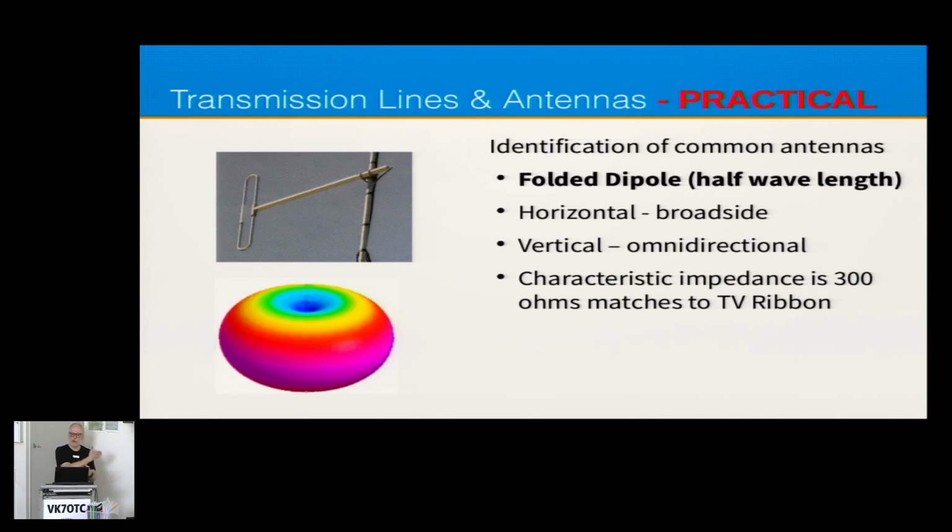Whereas if you turn it so that it's horizontal, it's actually a broadside antenna that is in two different directions. And then if you turn it the other way, you've got slightly different polarisation. So they're very versatile and very robust antennas. They can take a lot of ice when they're on a mountain. They're very, very popular commercial antennas.